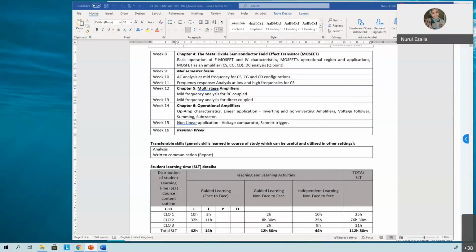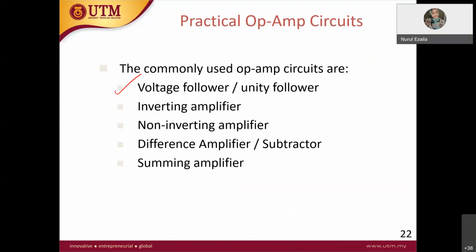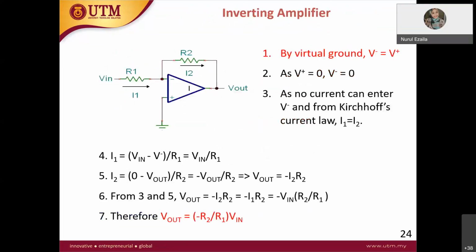All right, okay, let's take a look over here. For this type, number two, is the inverting amplifier. So how the circuit looks like from the name itself: it is inverting. Therefore your V in is connected to the negative of the op amp, but in this case V plus is connected to the ground. That's why we call this an inverting amplifier.